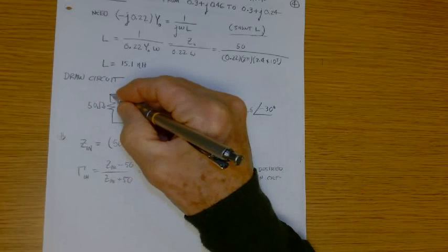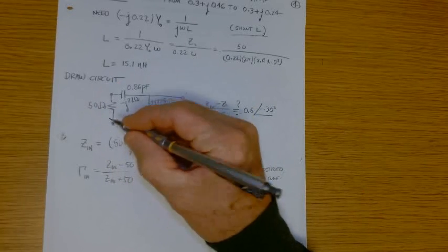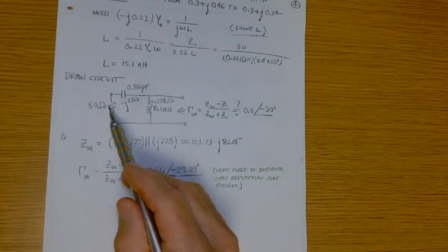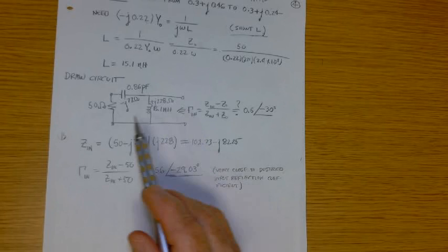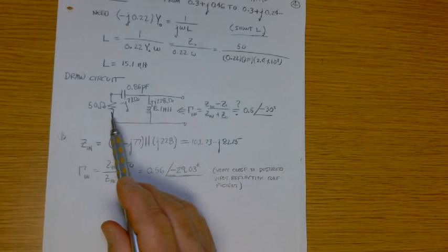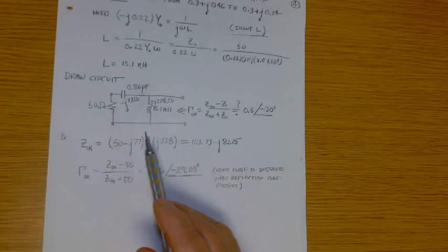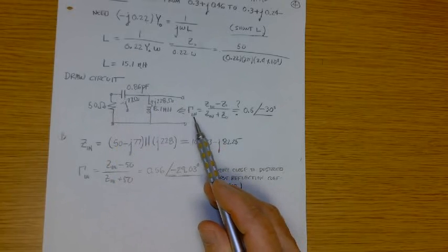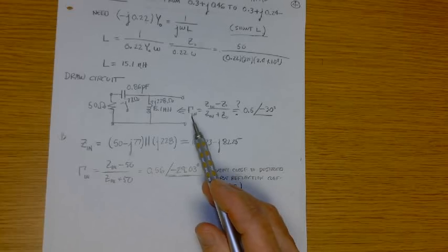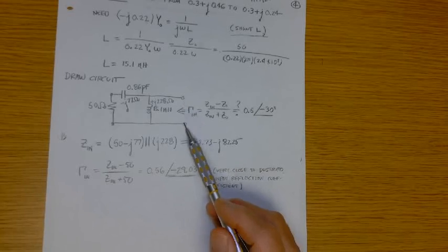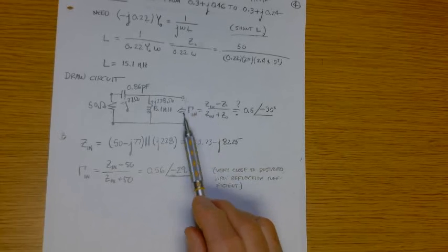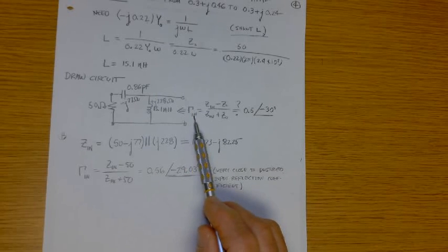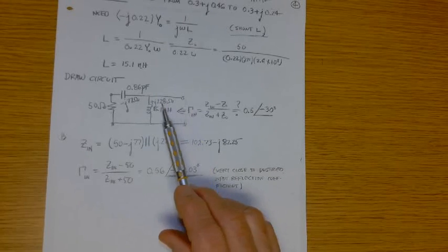It's a little different from matching. Before, we had some complex load and we wanted to make sure the input impedance was 50 ohms. Not this time. We're starting with a 50 ohm load, and we want to adjust these elements so as to give us a reflection coefficient that's the conjugate of what you see looking into the transistor where this thing's going to be attached. The transistor is that way, looking to the right of this pair of terminals. So again, we want this. The question is, did we do it right?